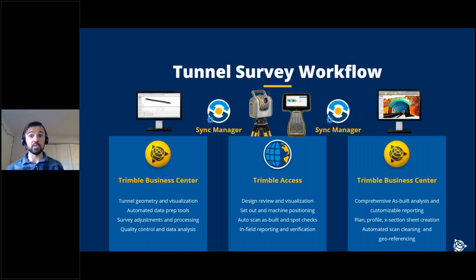And then the final piece, which I think is really powerful, especially used with the SX12, is the scanning tools. So the automated scan cleanup, removing all the parasites and the noise from the scan data so I can get to the deliverable faster. And of course, the automatic georeferencing using the SX12 or SX10, where in that survey workflow, we still take all of the backsite, the resection information, and it's coordinated with the scan. So if I have to update my control information, that scan data moves with my control. So really building that confidence on all of the data in one environment. So that's looking at the workflow from a high level.